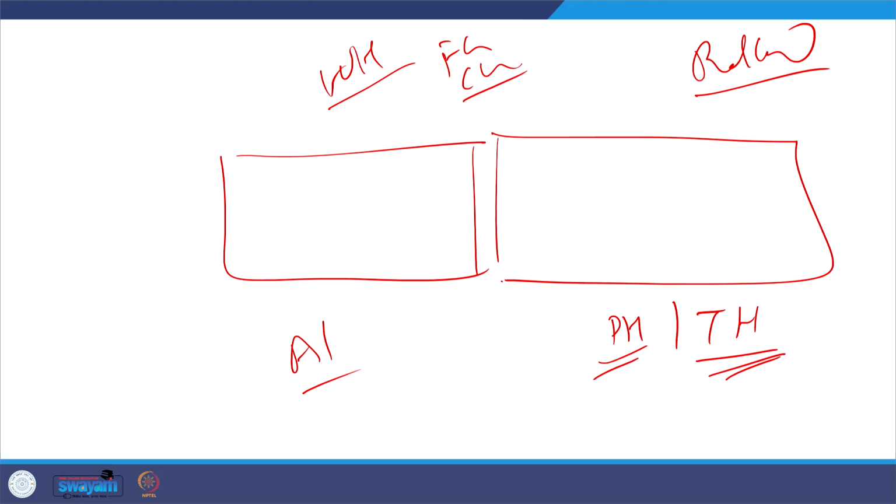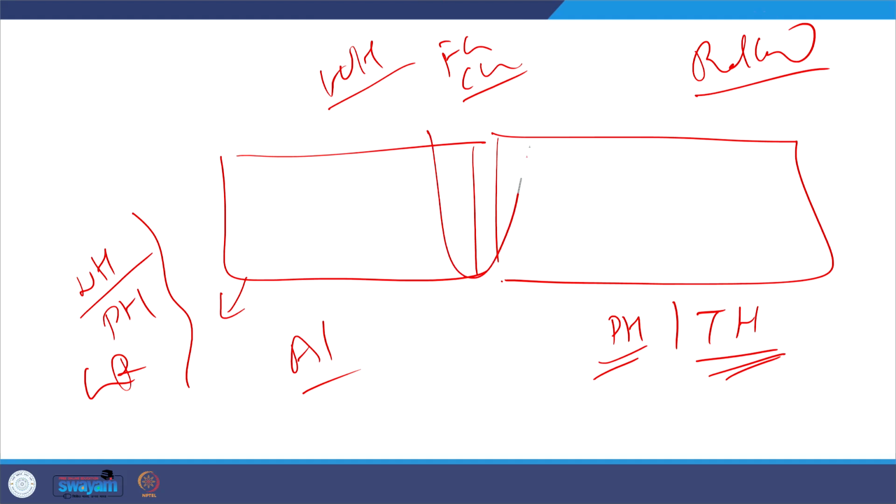The point here is, it is possible that a metal performance will be dictated by the multiple factors, like due to the rolling it is having the work hardening effect, and due to the presence of precipitates as per the design it will have the precipitation hardening effect, and it is possible that the grains have been refined, so the grain refinement effect. But when we apply heat, it is possible like precipitates will get dissolved. Say in this particular case there are fine precipitates coupled with the dislocations, of the fine grain size. So all these things will be compromised when the heat is applied during the welding.